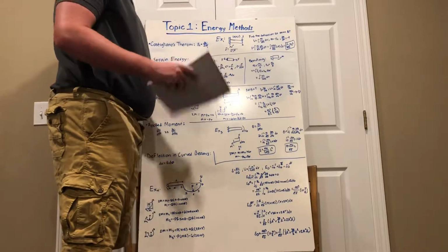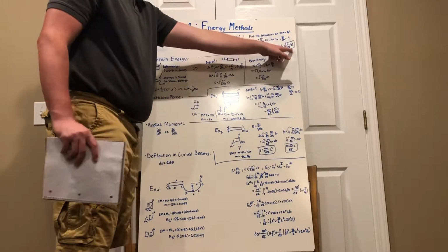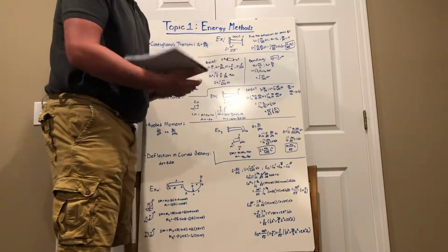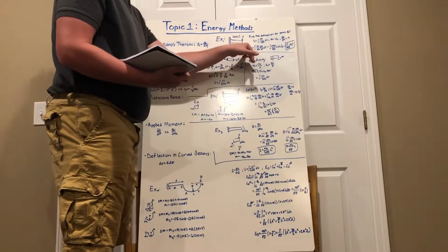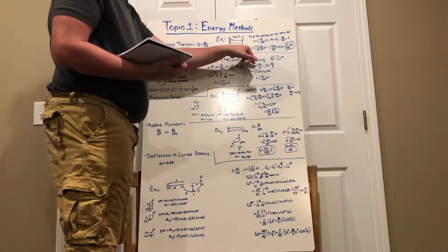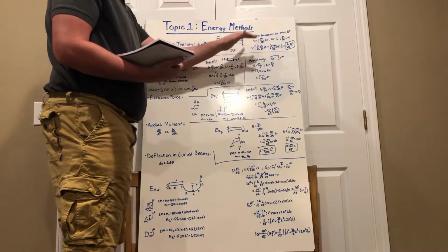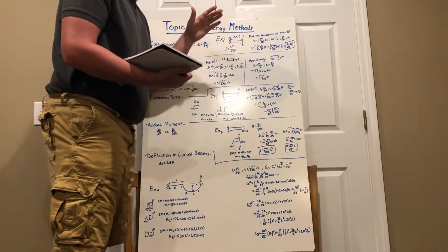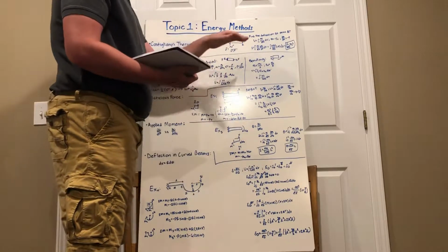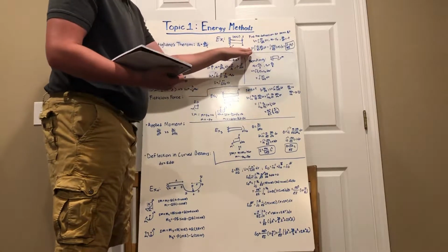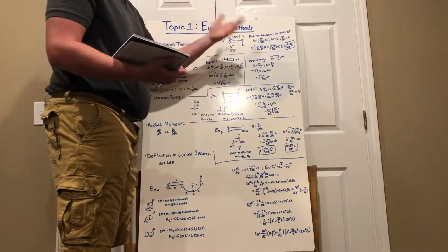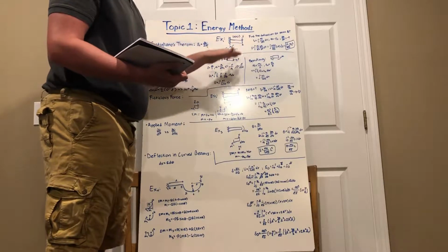Now, what does that mean? It means that the deflection at this point is based off of the force, the length, and these material properties, and we found this out by using energy methods. If we would have used typical means like we've learned in classes like dynamics, we'd have had to go through several more iterations of derivatives and second derivatives just to get our answers, and then we'd have to find constants as well. So this proves that Castigliano's theorem, or energy methods, is a faster and sometimes more efficient way to find deflection in beams.